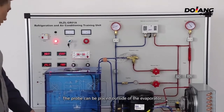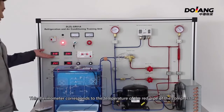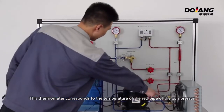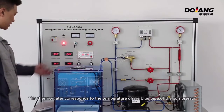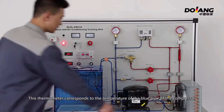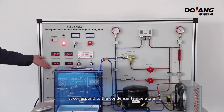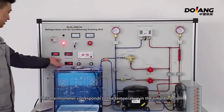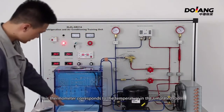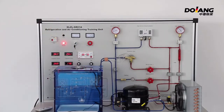The probe can be placed outside the evaporator. This thermometer corresponds to the temperature of the red pipe of the compressor. Its temperature will rise later. This thermometer corresponds to the temperature of the blue pipe of the compressor. This one corresponds to the condenser temperature. This thermometer corresponds to the temperature in the simulated room. The fan speed can be adjusted by the knob.